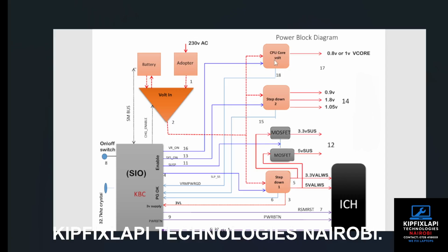Whenever you see any stacked inductor within the laptop motherboard, every stacked inductor contains a circuit by itself. So every stacked inductor you see represents a circuit. This step down circuit represents a PD controller IC or MOSFETs. It represents some protection capacitors and resistors.